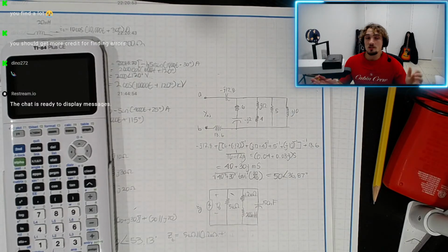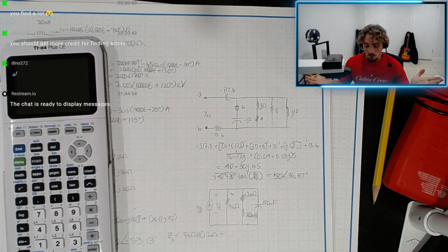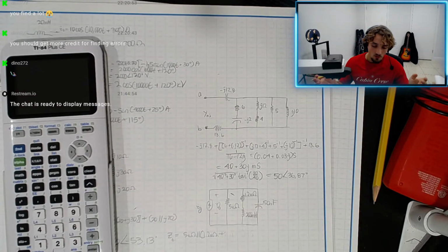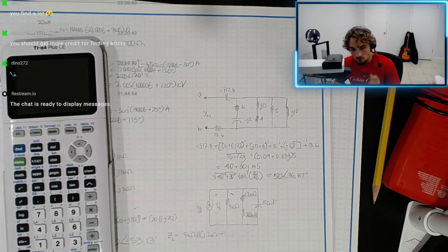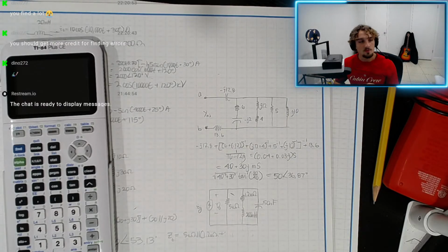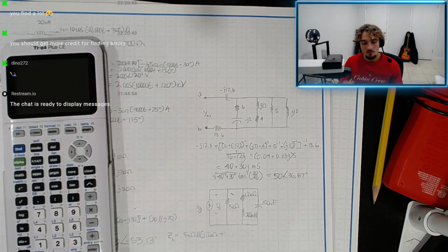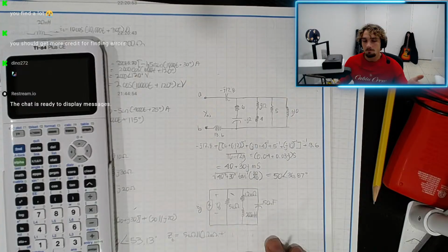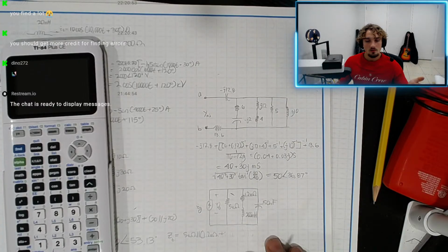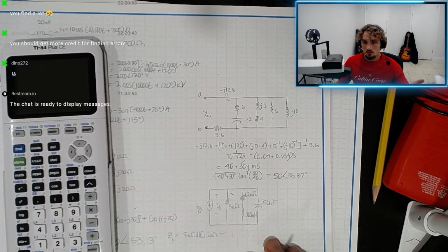So if our voltage is in phase with our current, therefore there's not going to be any phase shift. And if that's the case, then we're only experiencing purely resistive impedances. Therefore, we shouldn't take into account either of the other branches, just 5K.